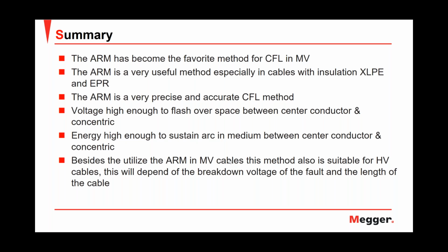And besides utilizing the ARC reflection method in medium voltage cables, this method is also suitable for high voltage cables. This will depend on the breakdown voltage of the fault and the length of the cable.